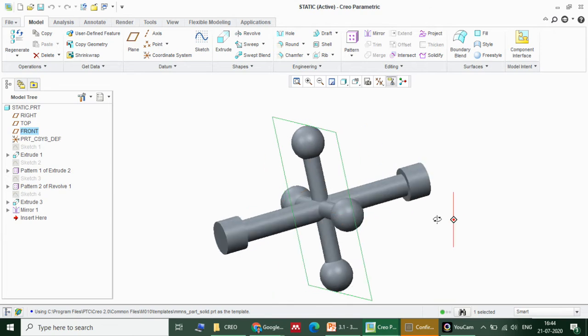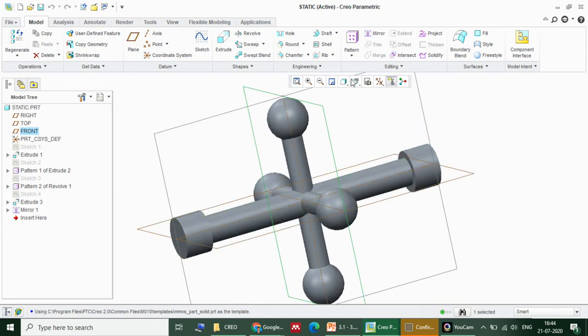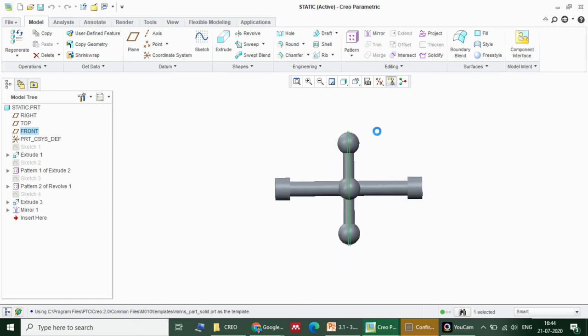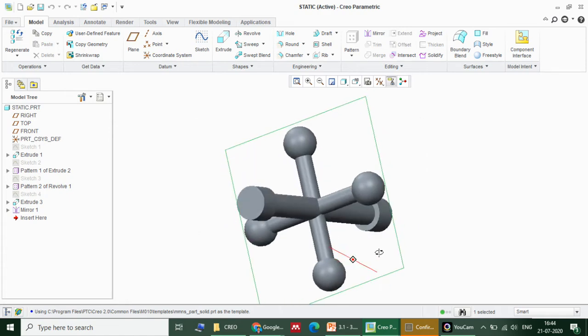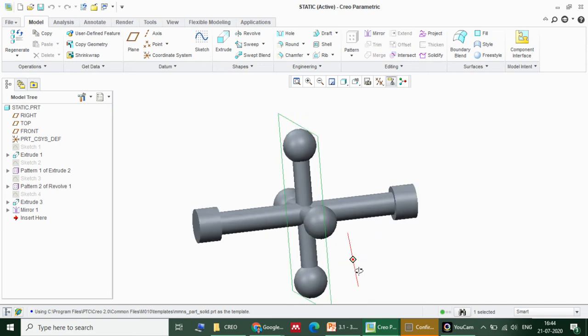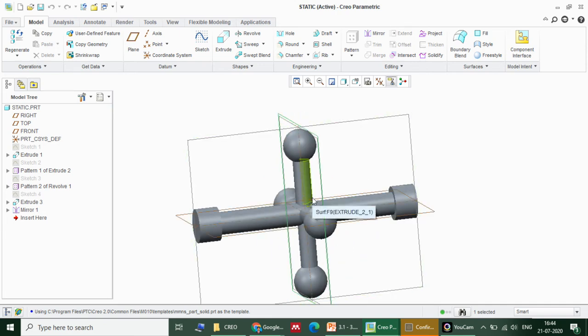Now, when all the masses under consideration, under discussion, under calculation lie in a single plane, or all the center lines of the masses lie in a single plane as in this diagram, then the balancing that you have done is called static balancing. Very simple. If all the masses lie in a single plane, disturbance occurs only in the middle of the shaft or one third of the shaft or only one place, and you put the balancing mass also in the same plane, then it is your static balancing. Okay, let us look at this.